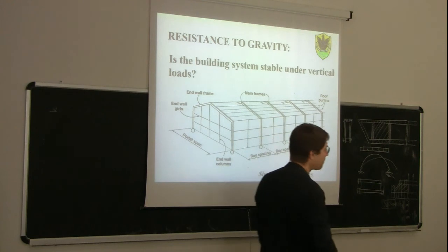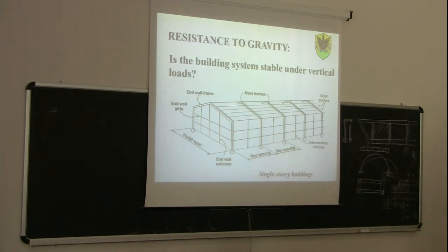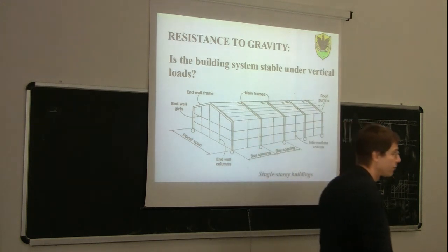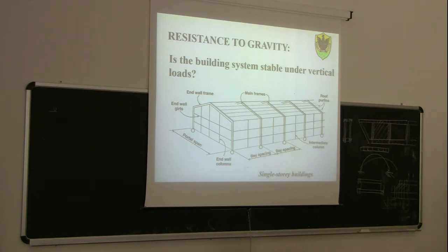Now, in terms of stability of the whole structure, in respect of three-dimensional stability of this structural skeleton, if we have, for example, these two-pin portal frames connected longitudinally using purlins, pins connected to the frames themselves, the first question we can ask ourselves is: is this building system stable under vertical loads? Is the system well designed under vertical loads? Do we have problems for resistance under vertical loads? What is your answer? Yes or no?